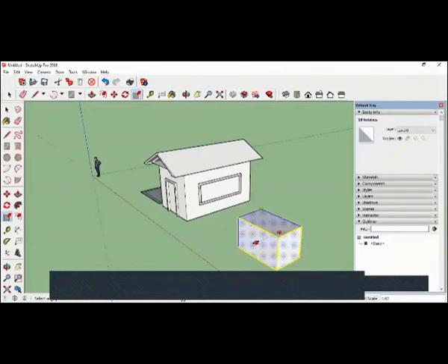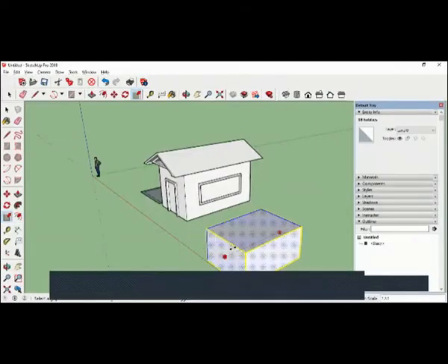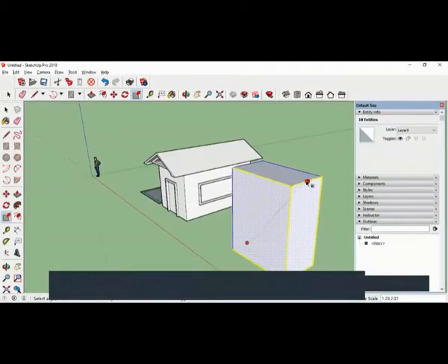Now, if you click this one, it is showing you green scale. That means you are increasing in the green direction. Okay. If you select this one, you are in the Z direction, blue scale. So suppose you want to change the scale in 2 directions, in red as well as Z. So I will hold here. And once you select this point, immediately the lower right corner is telling you red blue scale. So this is red, this is blue. We can change scale in 2 directions.